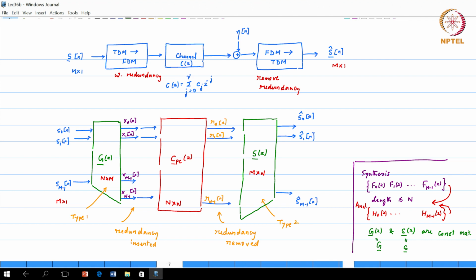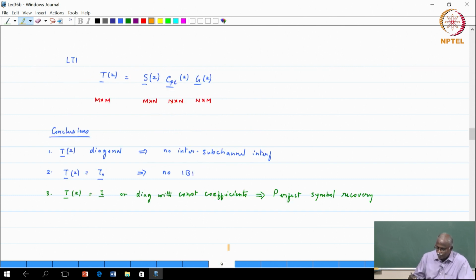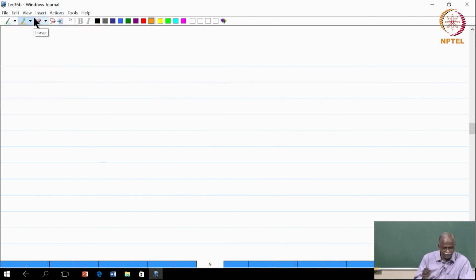Okay, so the process of simplification involved that we did the polyphase decomposition and also polyphase decomposition of the channel, which is what gave us the pseudo-circulant matrix, and yesterday we did an example of the pseudo-circulant matrix, and we also did some calculations on how to show that if I do zero padding, the interblock interference is removed. But what I would like to do is revisit that, because there were a few questions after class, maybe a little bit of clarification would be helpful.